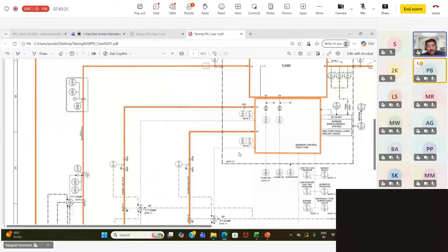Okay, although an on-off valve would have sufficed, since this is for a fuel gas system and a burner system, we have provided ESDs because all other systems were considered as still SIL 3. So here I'm saying you provide an ESD here, you provide an ESD here, and an ESD here. That is what you have to do as a part of the HAZOP recommendations.